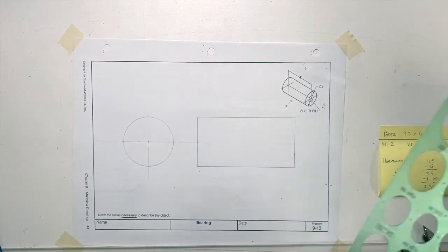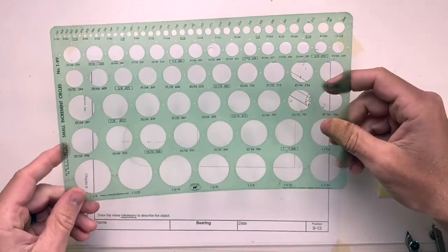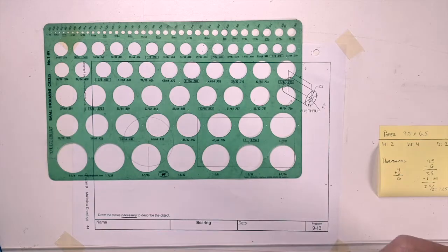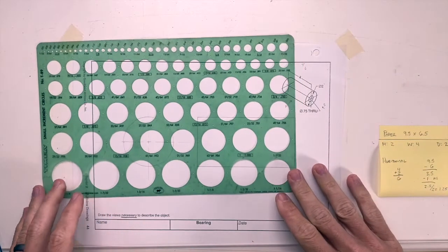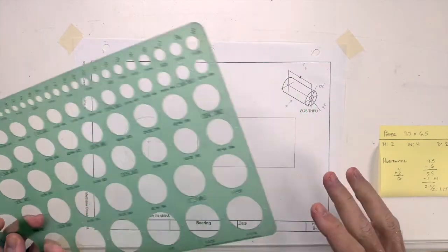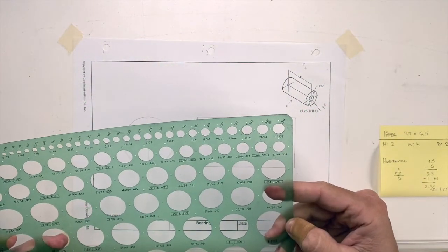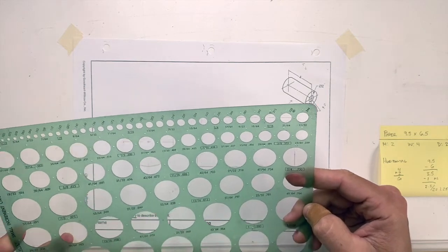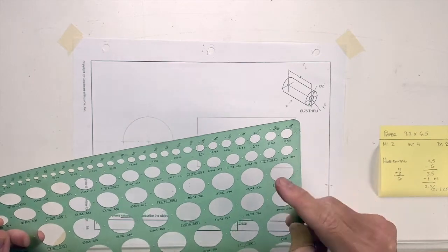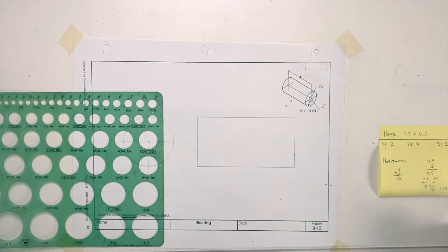So you have your circle stencil, and yours might look a little bit different than mine. But to use this, and you could use your compass, but it gets a little tricky when you're doing small circles, and this one's kind of right in the middle. So for this, you're not looking for a radius anymore, you're actually looking for that diameter. So I'm looking for 0.75 or 3/4 of an inch. So there are quite a few circles on here. Here is my 3/4. So when you use this one, let's get our other tools out of the way.